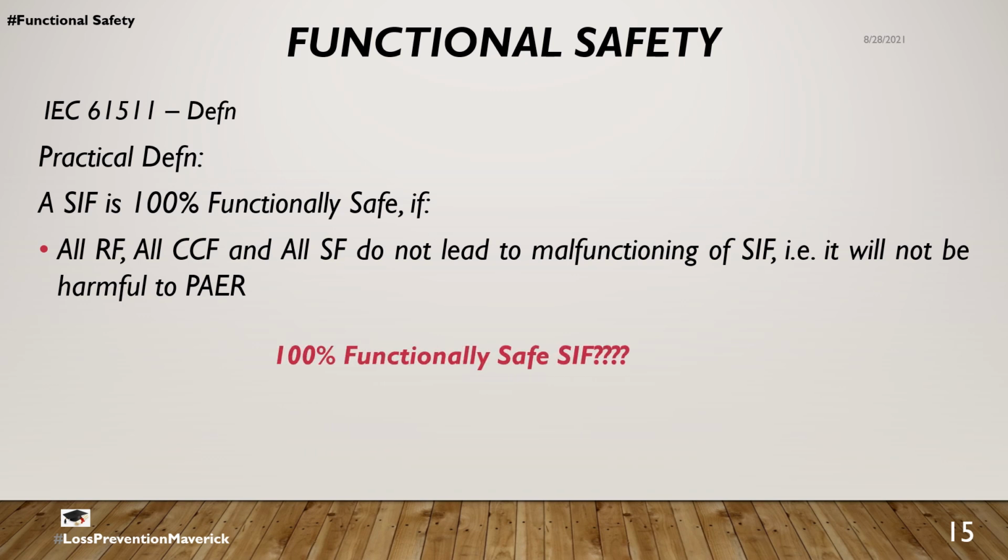So now let's say, can we guarantee a 100% functionally safe SIF? Well, we cannot. Why? Because we know that there is no way of avoiding random hardware failures or common cause failures. It cannot be controlled. So this is where the whole definition of SIL comes to importance, because SIL is a performance standard which clarifies the performance of a SIF to function on demand irrespective of all the occurrences of random, common cause or systematic failures.